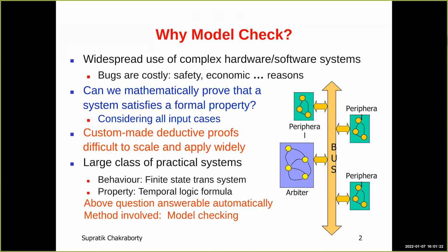One might say that sequential equivalence checking is one extreme case of reasoning about sequential behavior, because there we are trying to check whether two finite state machine implementations have exactly the same sequential behavior, which means they have exactly the same state transition diagram. That's kind of a hard problem.